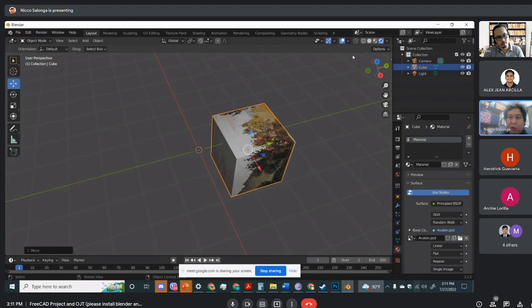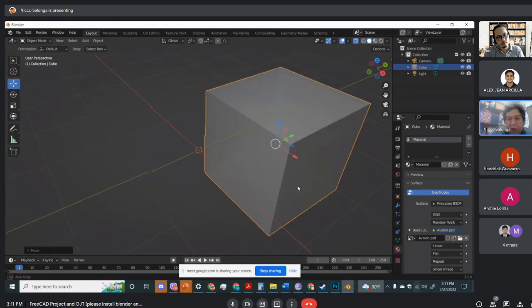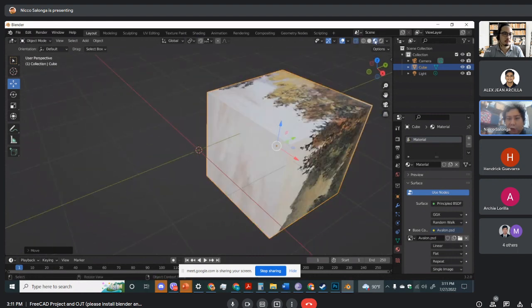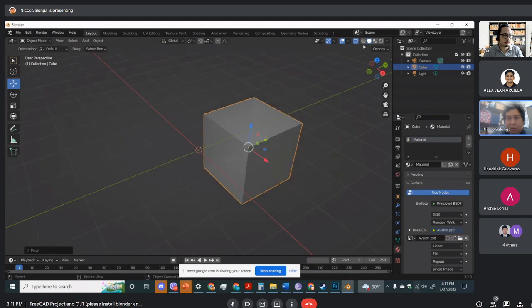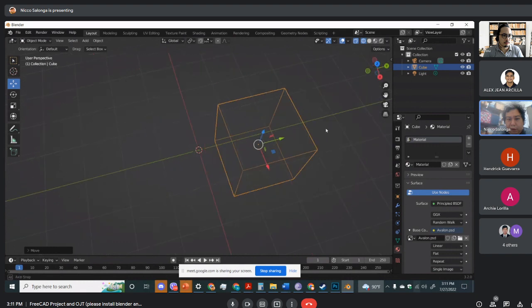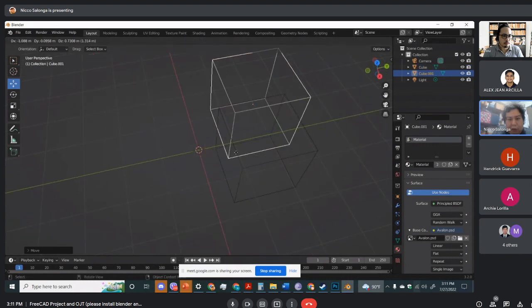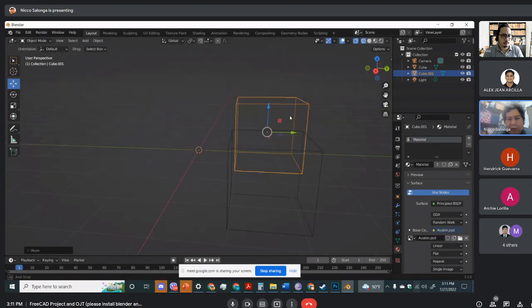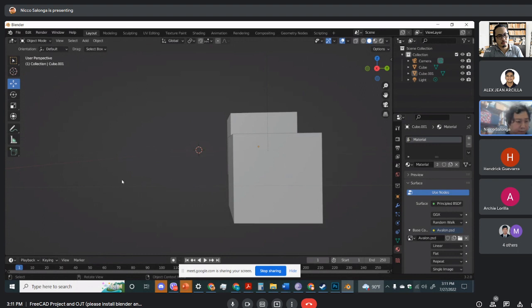So there's also X-ray view. It lets you, for example, look through the object when you're working on it. It will show things behind it as translucent. For example, let's say we duplicate this and have them behind each other. If you're in this view, you can kinda see it, but if you press the X-ray off, you can't.